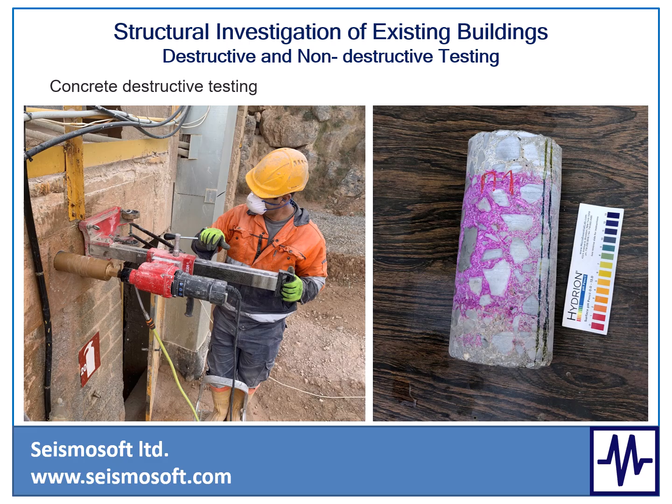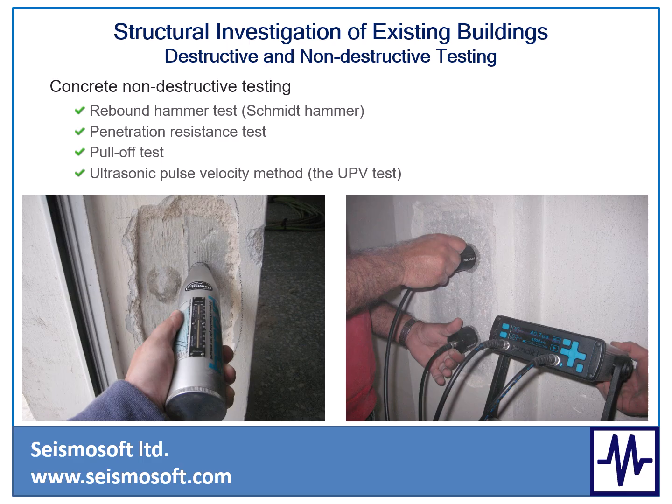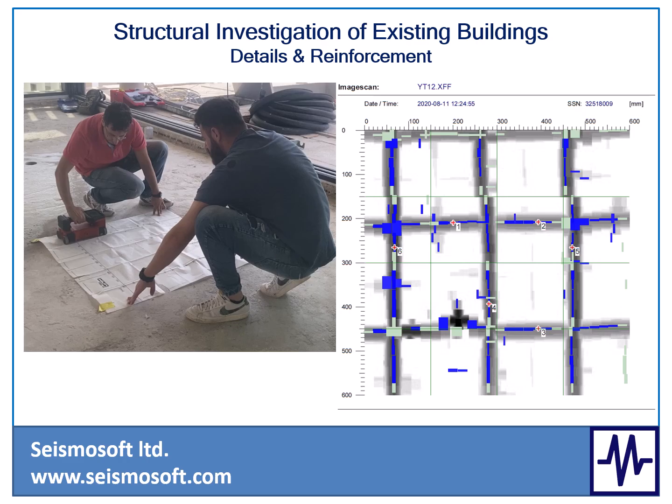The details of a program for experimental testing in a typical building will be given, and the destructive tests for concrete, steel, and the infills will be presented. Furthermore, information on the concrete non-destructive testing will be provided, as well as information on how to scan the reinforcement of the concrete members with the typical ferro scanners that are available in the market.